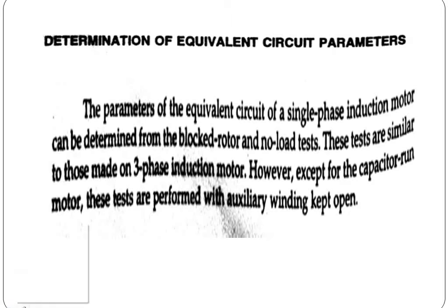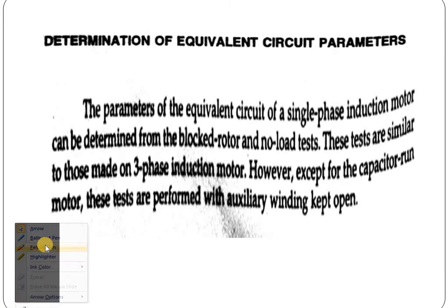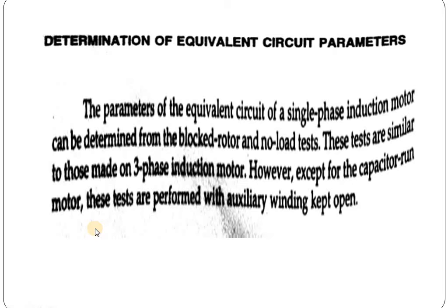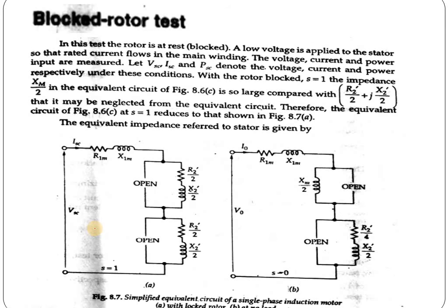For other types of single-phase induction motor, it is sufficient to perform the test with opening any of the terminals. So let us start with the block rotor test.